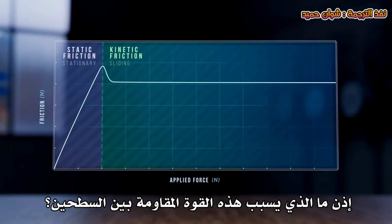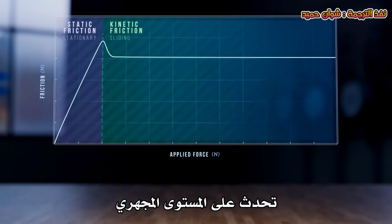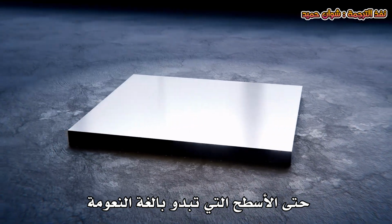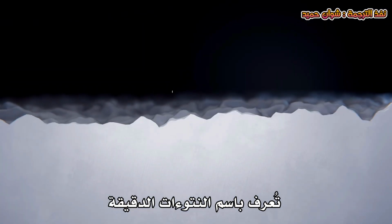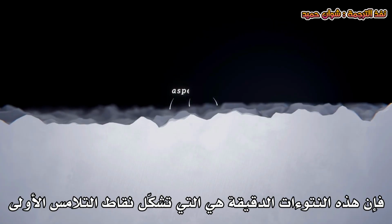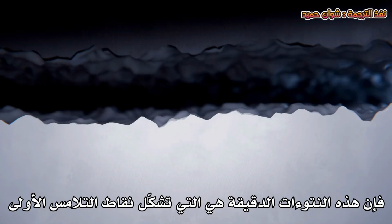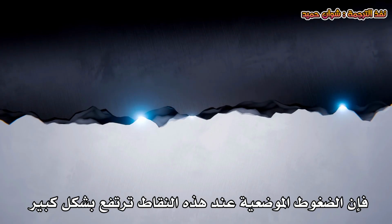So what causes this resistive force between the two surfaces? It turns out friction is the result of some quite complex interactions that occur at the microscopic level. Even the most smooth-seeming surface, if you zoom in close enough, is covered in microscopic peaks and valleys, called asperities. When two surfaces are brought together, it's these asperities that make the first points of contact. Because the load is supported by just a few microscopic regions, the local pressures at these points get really high.